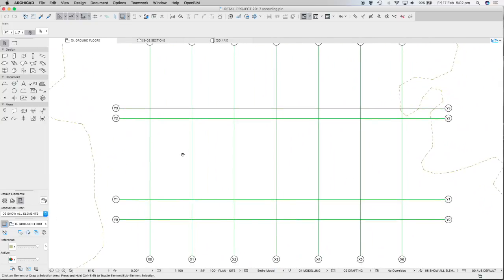Now we're going to put some pad footings in. Mainly their purpose is to support the concrete tilt-up walls. And I'm thinking a 12 metre length of wall, we're probably going to want another footing in the middle and a split wall panel in the middle. So we need another grid line in the middle here.